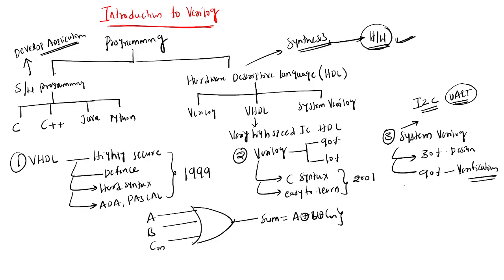That's why we go for UVM, the Universal Verification Methodology. This is not a language, it is a methodology. You use SystemVerilog in UVM, and with some modifications, a test bench you wrote earlier can be reused for UART. That is standardized, and any company will write test benches using UVM.